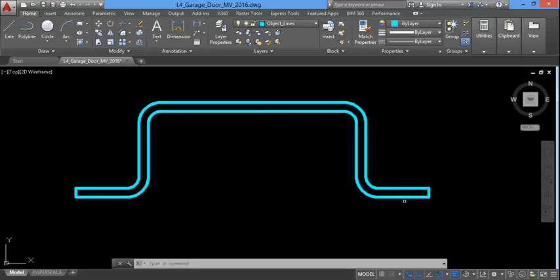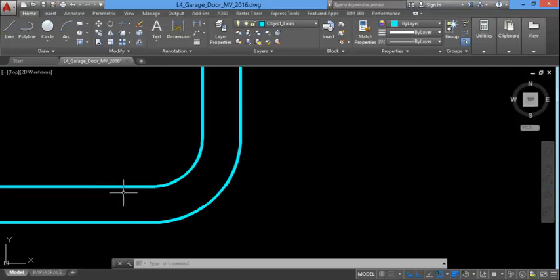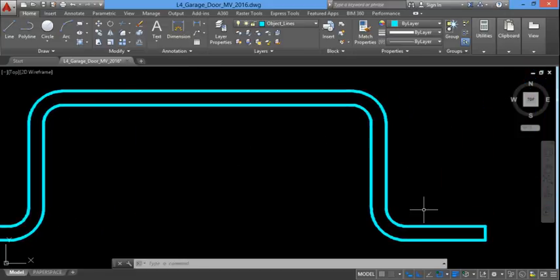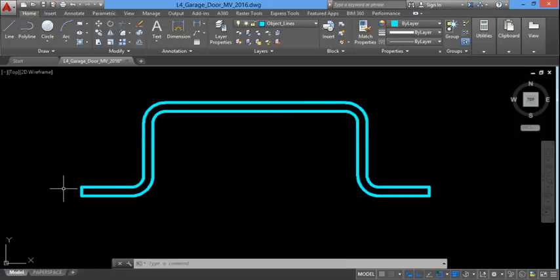In order to extrude an object to become a solid, the entire path needs to be continuous. What's called a closed loop or region, R-E-G-I-O-N. There's different ways to get a region, but for a region to be successful, there needs to be no extra pieces of any parts that were not trimmed or any gaps in the drawing that will prevent a region from being formed. If you have any two-dimensional drafting problems, then the three-dimensional version of this will not be created. So keep that in mind.